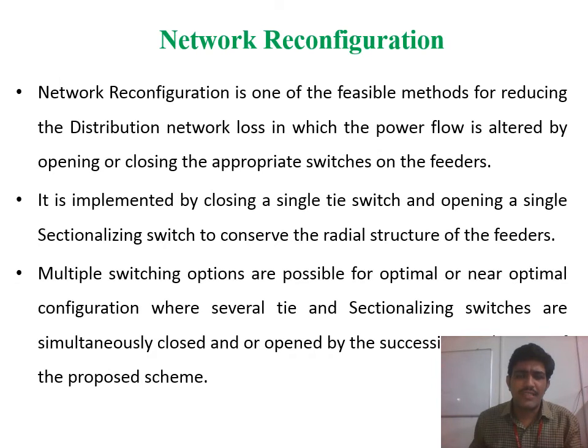Before network reconfiguration, we have to apply the load flow analysis to compute the voltage stability index at different buses. After reconfiguration, that is, the method of regulating the structure of a feeder in the distribution system by altering the positions of tie switches and sectionalizing switches, meaning closing and opening of the switches at one case only.